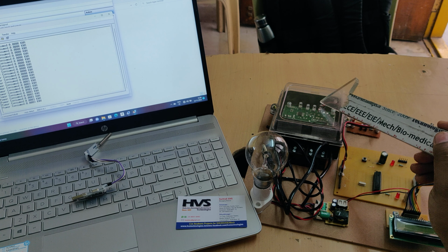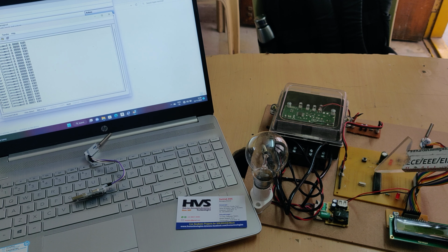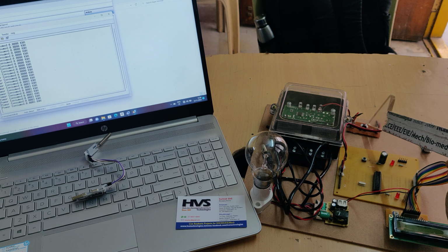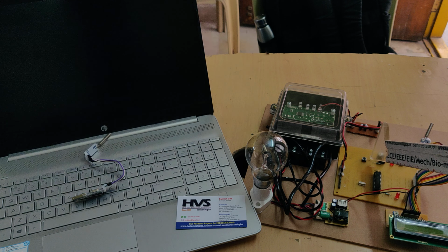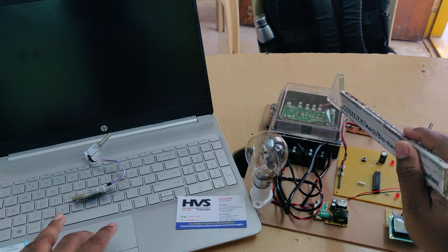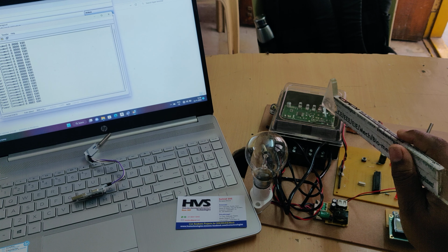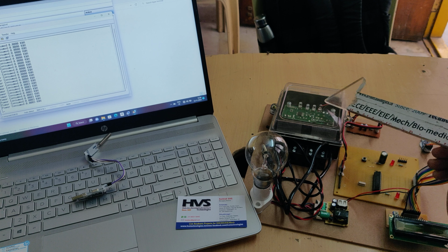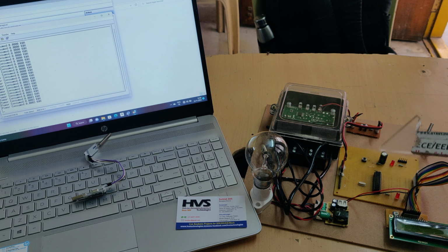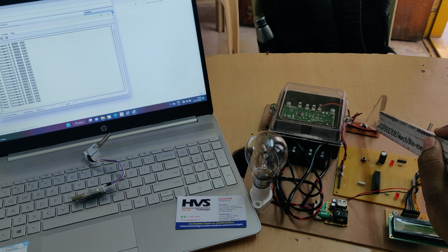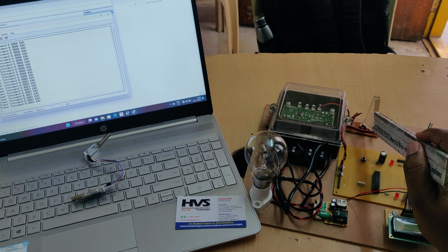Instead of giving the LED output directly to the microcontroller, we placed an optically coupled optocoupler in between the LED and the microcontroller. If any high current was generated from this current meter LED, and we connect that directly to the microcontroller, then the main controller will get damaged. So in order to protect that, we place the mediator IC, that's an optically coupled one.